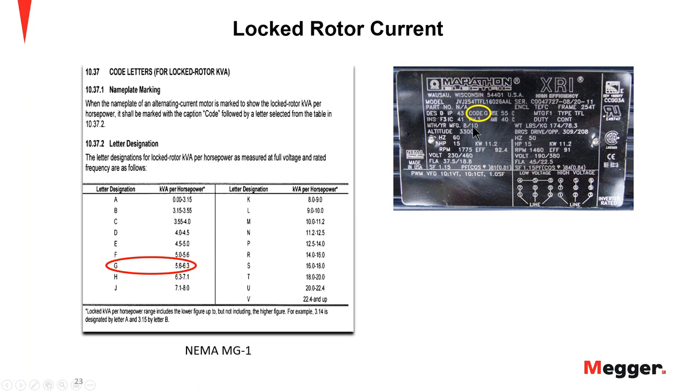And one thing I will say is there's a lot of information going on in this nameplate, and it's very busy. Just make sure that you're reading the correct code. If you're not reading the correct one, and let's say you get off and you're on B, then you think this is it, and you end up cross-referencing B, you end up underprotecting the motor itself, or you could cause false tripping, or all types of different events. So you want to make sure that you are reading this nameplate information correctly and cross-referencing these numbers, because there's a lot going on in these nameplates.